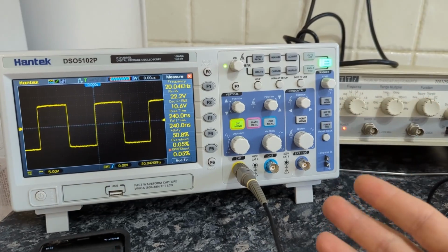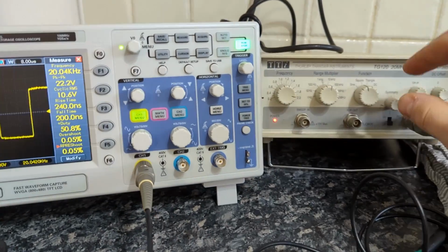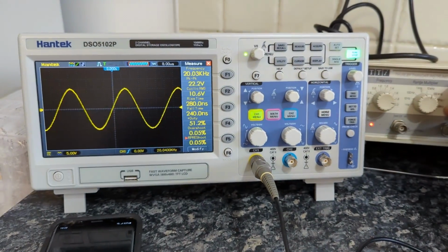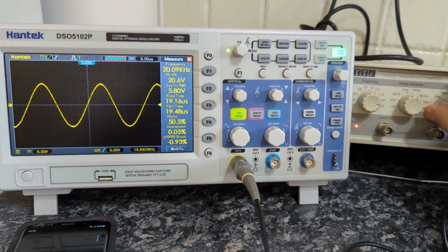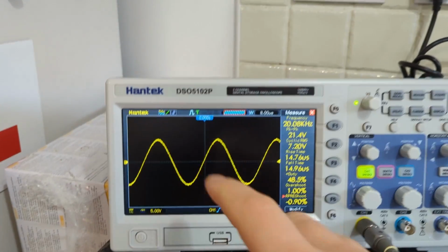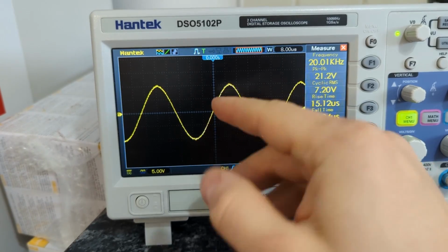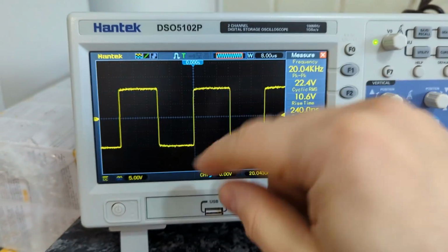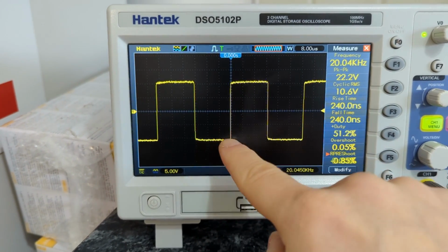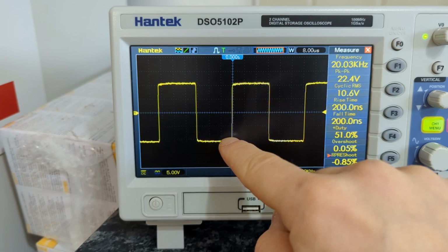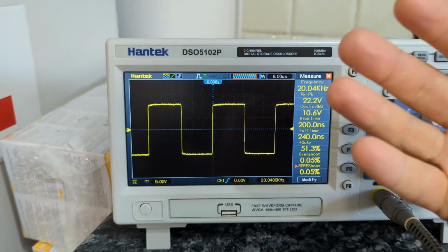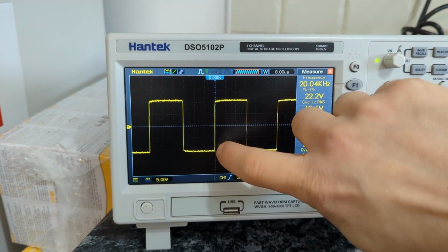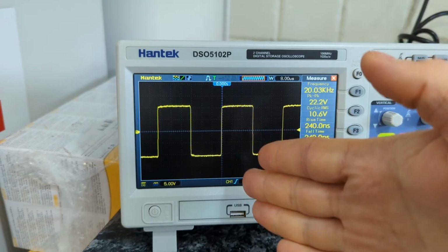So let's talk about the slew rate and what it actually is. I do have this generator that can generate various waves. So I have sine wave, square, triangle. On a regular sine wave, you have peaks and dips, and it's just a regular sine wave. If you look at a square wave, it has extremely sharp edges. Basically, a square wave in an amplifier would represent an infinite impulse. So the first edge should be infinitely steep.